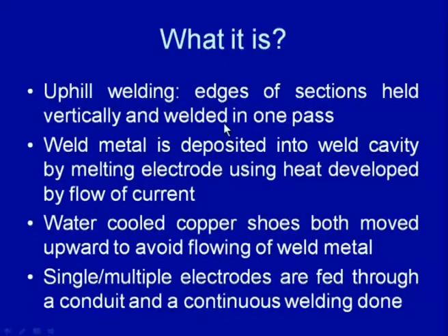We will go one by one through the need of this process, the process capabilities and the principle of this process, and the various advantages and disadvantages related to this process. This process is typically characterized as an upfill welding process, because during welding the weld joint is made in the vertically upward direction. So, the edges of the plates to be welded are brought into aligned state vertically, and then the joint is made in one pass.